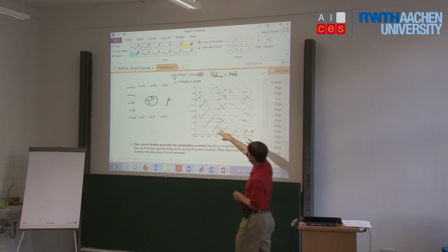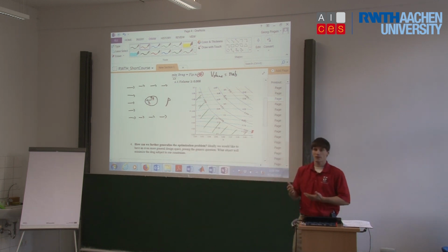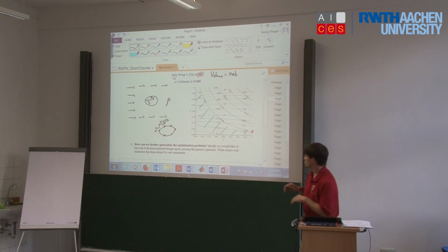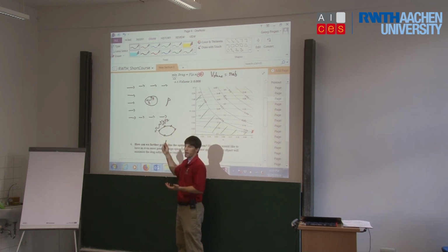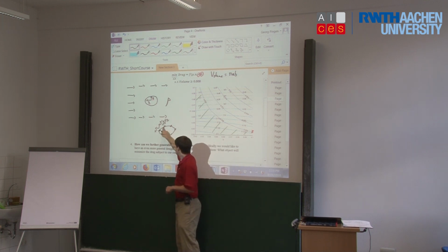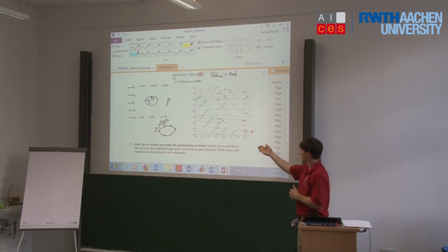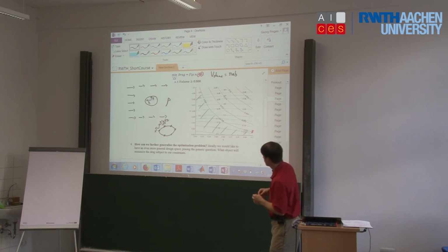We only have two parameters. We could take this shape and parameterize it with multiple points. So we could have some shape like that, which starts out looking like an ellipse, and we could use several points along it, and at every point we could move the point: y1, x1, y2, x2. So we could have these 6 points. We could map some spline, some curve that connects these points based on the coordinates. And our design variables could be the x and the y coordinate of each one of these points. And now our optimization could try to find the best combination of these total of 12 values.